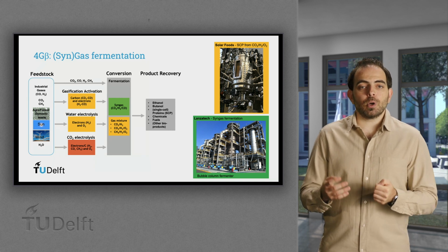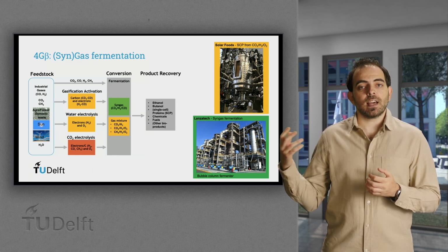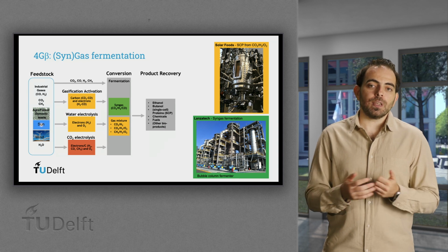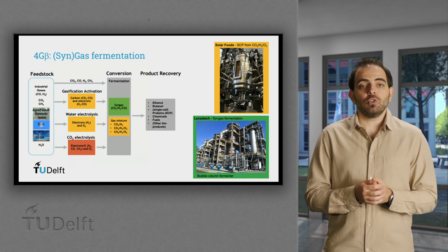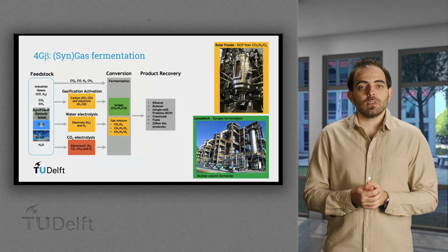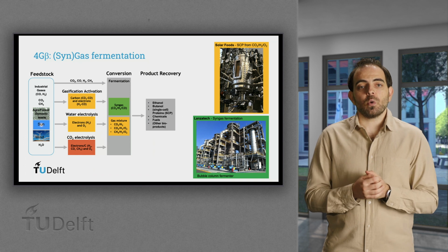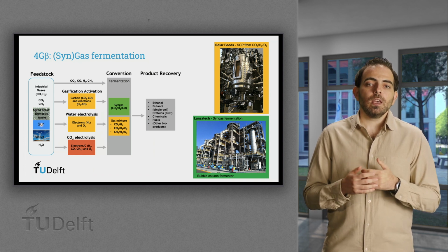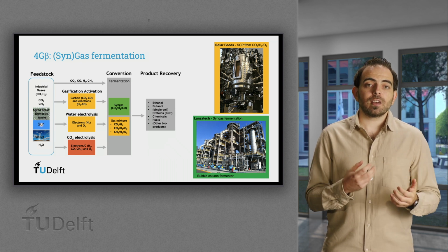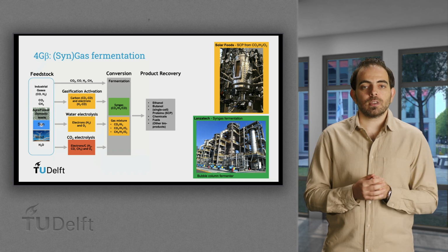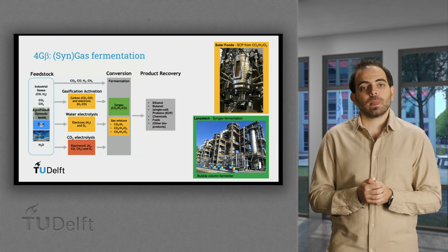For example, some startup companies develop fermenters converting mixture of CO2 and hydrogen to products such as alcohols. Other startup companies develop gas fermentation converting mixture of CO2, hydrogen, and oxygen to either feed or food ingredients. The main challenges of gas fermentation regard gas-liquid mass transfer and safety when oxygen is present. These gas fermentation processes offer the opportunity to valorize carbon waste and indirectly renewable electricity to a wide range of products of interest, while not relying on agriculture nor on fossil resources.